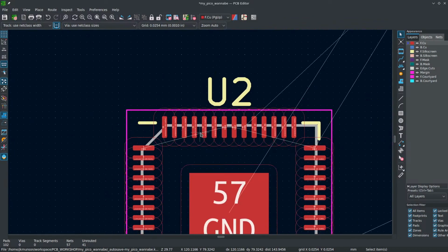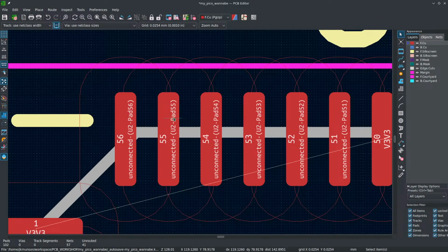The reason I said I will probably solder these is because these pins are so close together and don't have solder mask. They're really hard to get right. So when I get the boards, I'll sit down and solder the controller on for all of you, unless somebody really wants to do it themselves, that's fine too. This is something where the automated manufacturing process can probably get it perfectly fine, but if you haven't done it before, you're probably going to end up frying a bunch of boards. Because that's what I did the first time I tried something like this, I fried quite a bit of stuff trying to get it to actually work out.